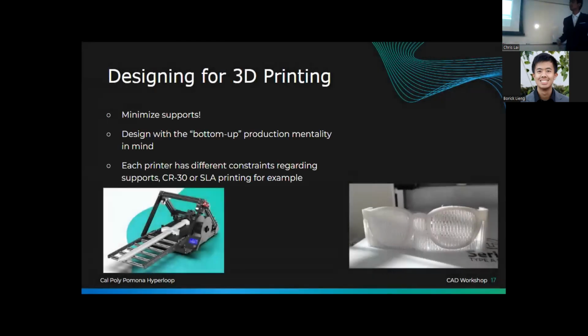All right. For 3D printing, when you design something, you want to make sure there's the least amount of supports possible. The supports tend to fail a lot, as you can see right here. These are all support material, and if any of those fail, the entire print will fail. You want to make sure you have a flat base.